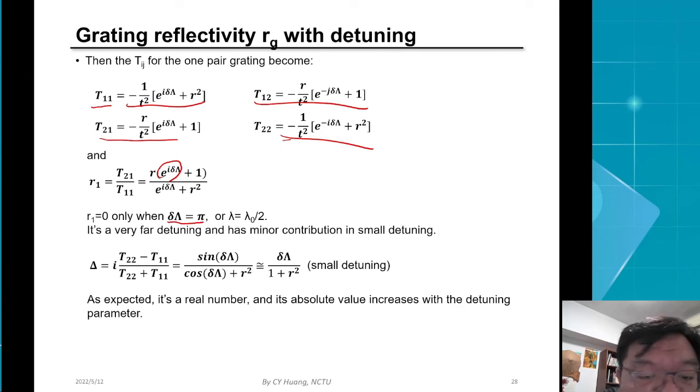That gives the AR condition when the wavelength is half of the Bragg wavelength. But this is not precise, because at half the wavelength the refractive index will be pretty different, so this is not the point of interest now. What is of interest is when the wavelength is close to the designed Bragg wavelength. So let's see what happens with detuning.